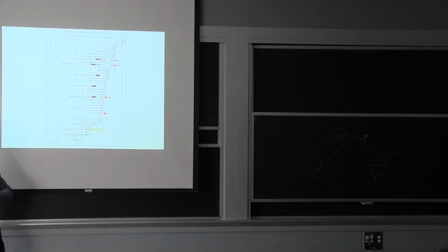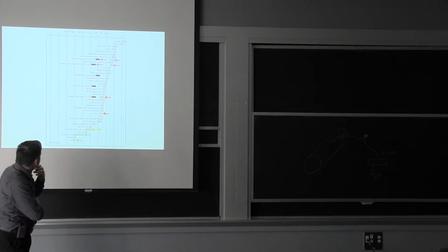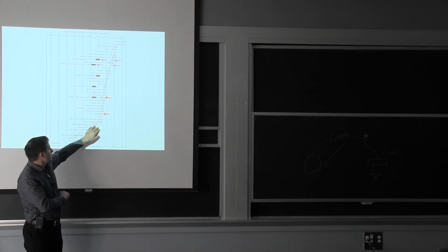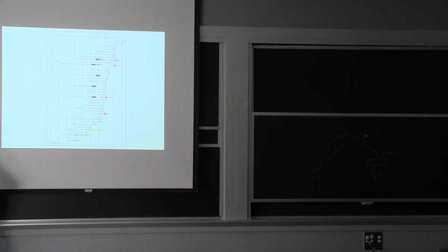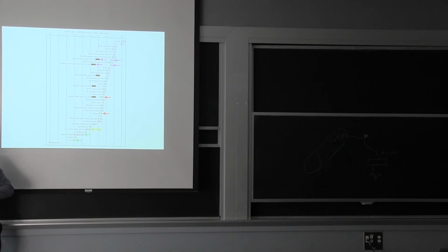Yes? So if we're trying to predict the behavior, what happens in the Statue of Liberty, we look at the copper and the iron steel here, and we see that the copper is further to the right, and therefore it's going to be passive, and the active material, the one that's going to turn into an ionic zone, is the iron. So we're lucky for that with the tower, because at least we don't lose the face of it. It's just locally where these ties are connected to the armature is where the corrosion localizes.